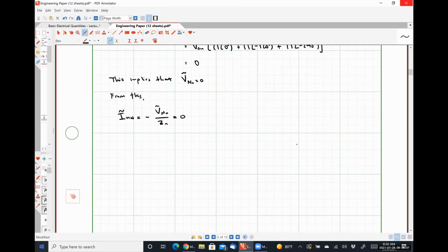All right, so our line current I_aA, which was V_AN minus V_Nn over ZWA plus ZYA, in a balanced system just looks like V_AN over ZW plus ZY. Our line current I_bB